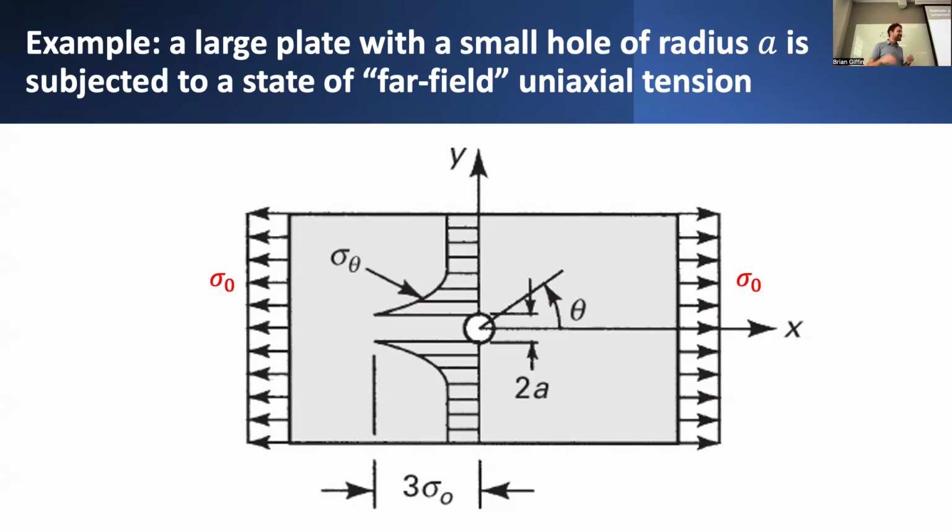Okay, having said that, what we want to know is, if I have some plate, and maybe for some reason I wanted to go to a bridge girder or some other kind of structural component, and I said, I want to drill a hole right here through the structure. I know it's already sustaining some loads. Maybe it's subjected to some uniaxial state of tension. Far away from the hole, the load can be idealized as roughly constant under uniaxial stress conditions.